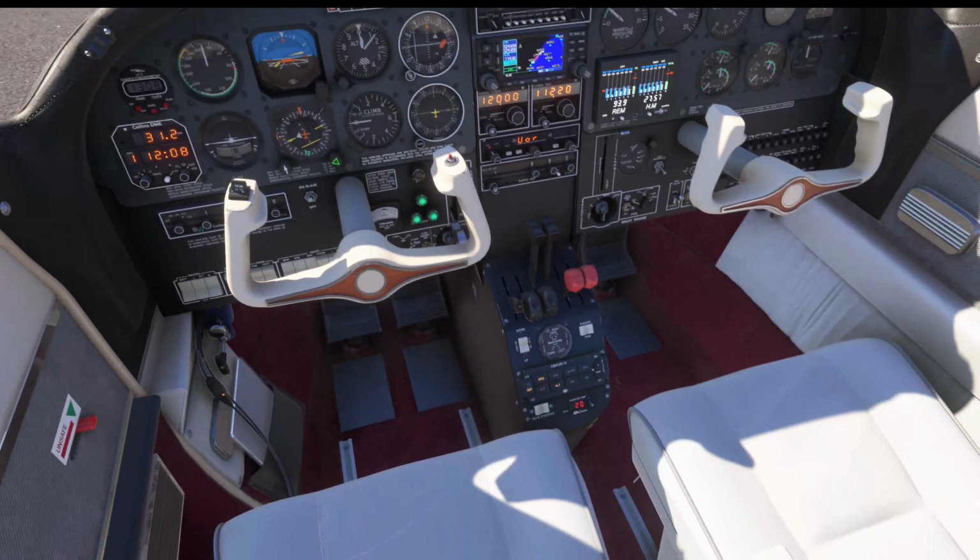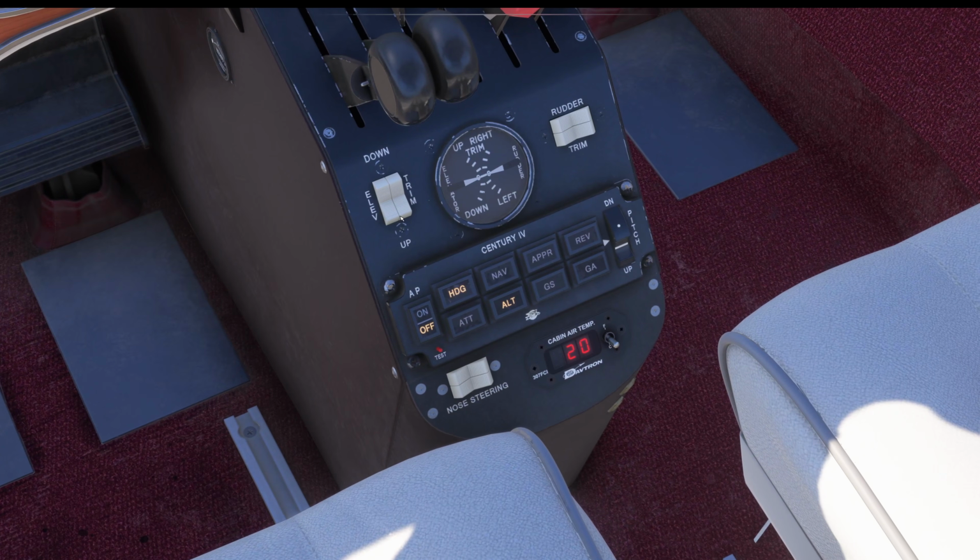The main autopilot panel is located on the pedestal. The 4 buttons in the top row select lateral modes, and the 4 buttons in the bottom row select vertical modes. The buttons cancel each other, so only one mode can be active at a given time. The exception is the glide slope button, which can be armed before glide slope capture, but for that we would need a valid glide slope signal. If you listen to how the buttons click, these are recordings from the real aircraft.